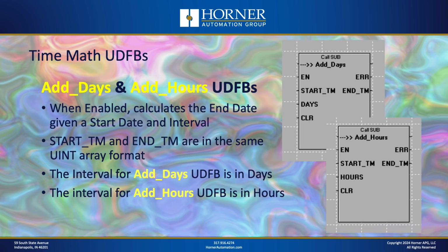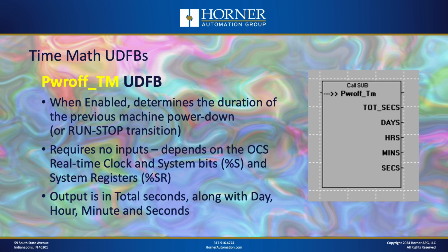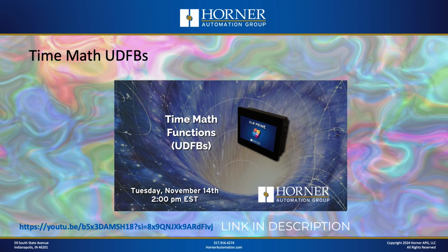We've also got a couple of add functions, one for adding days to a start time, another for adding hours to a start time. And in both cases, they give you the result in terms of the time and date when the end time will occur. So these are also very useful. And then we have our power off time UDFB. Again, this is the one where you may want to react completely differently with your control algorithm depending on how long a machine has been powered down. Okay, and then here's the thumbnail as well as the link for this particular UDFB category.